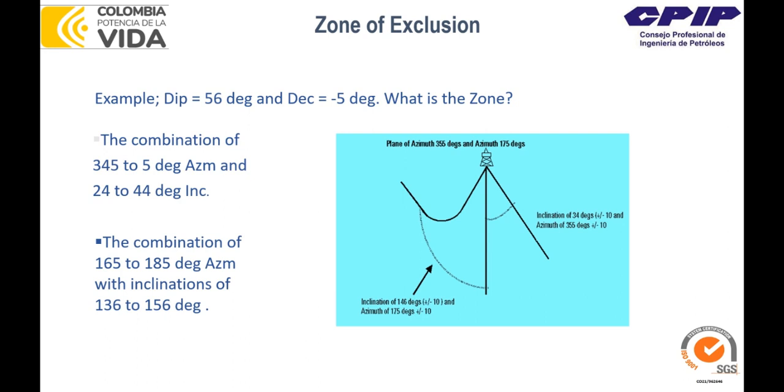So again, this is quite a steep inclination, and you're unlikely to see it in any of your wells. So not much to worry about for the northern hemisphere. The big problem is drilling horizontal wells at the equator in the southward direction, and drilling south in the southern hemisphere. Okay, so this topic seems a little bit complex, and it's actually not out of the competencies of a geosteering engineer. But just make sure you know that such a limitation does exist, and during your pre-job modeling, verify with the MWD engineer whether any zone of exclusion is expected to be seen in this upcoming well.